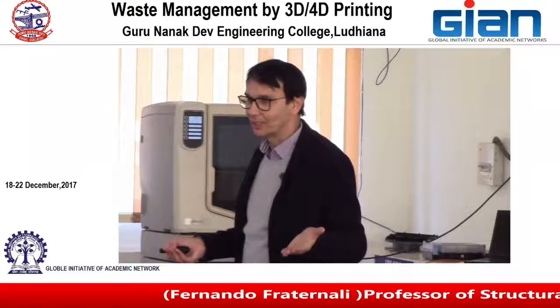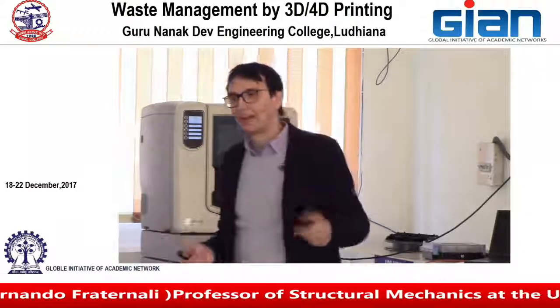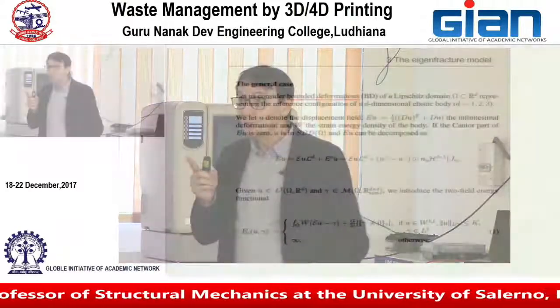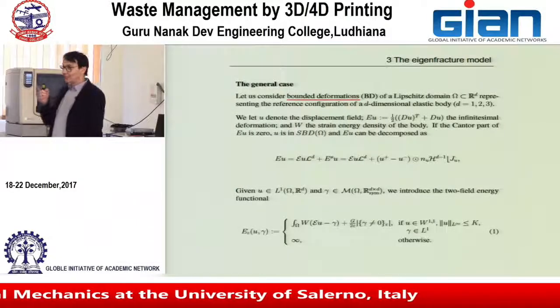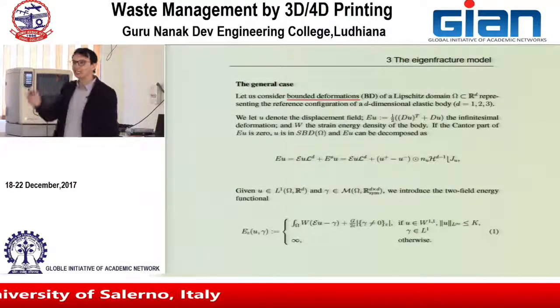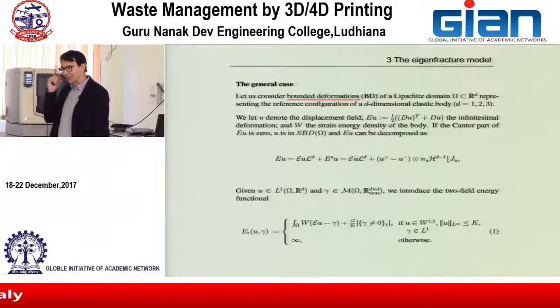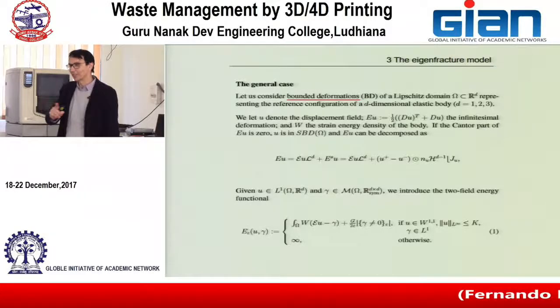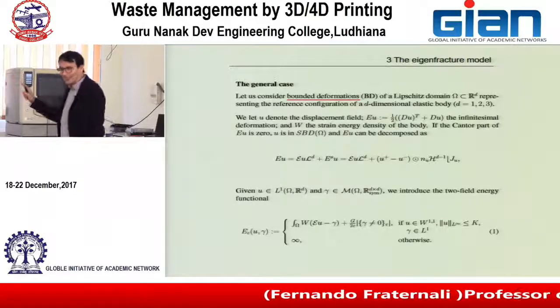Otherwise, it won't be killed. Okay? But how do you measure the energy that you need to kill the element? That's the trick. That's the trick that you have to learn, because otherwise this doesn't work.